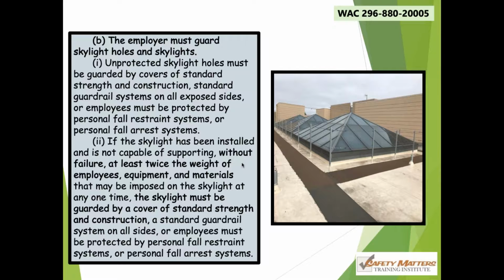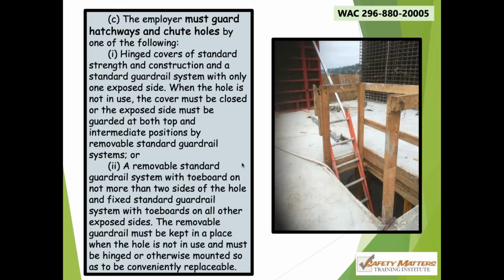If it cannot be capable of supporting that, then we have to do what? We have to cover it up. It needs to be guarded by a cover of standard strength and construction around all open sides. Hatchways and chutes, if you guys are going up there to the rooftop and you're still climbing up through an open hatchway, we need to protect these and make sure that we're not falling through those.